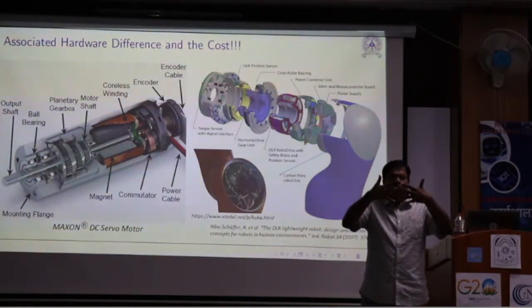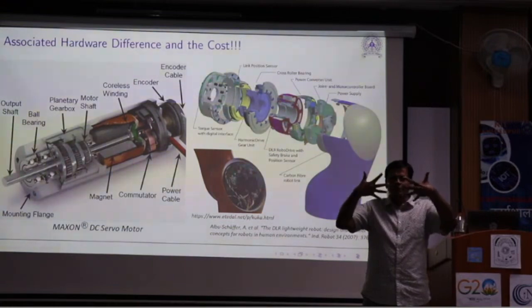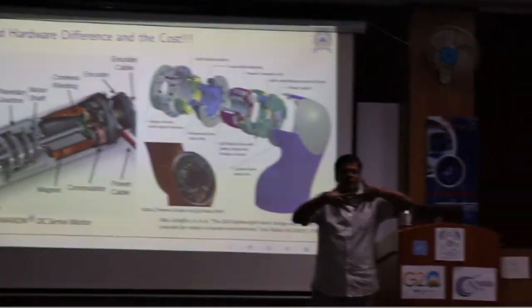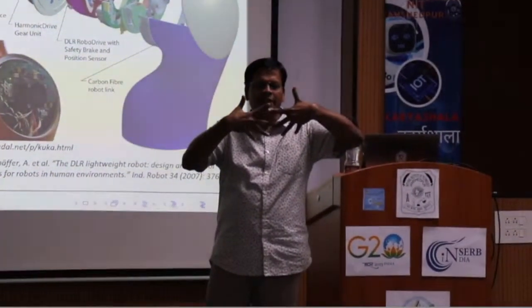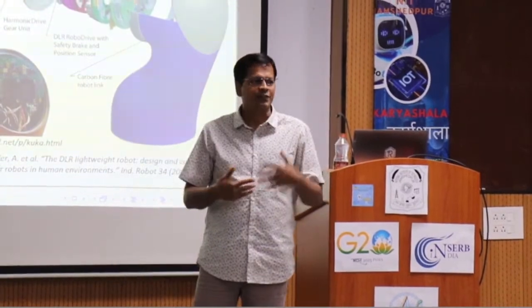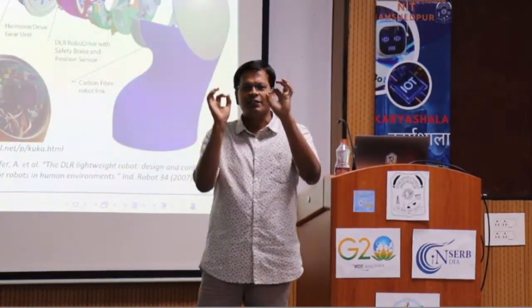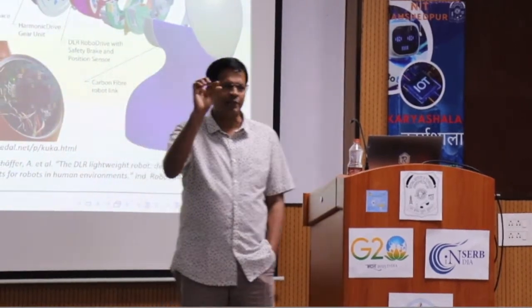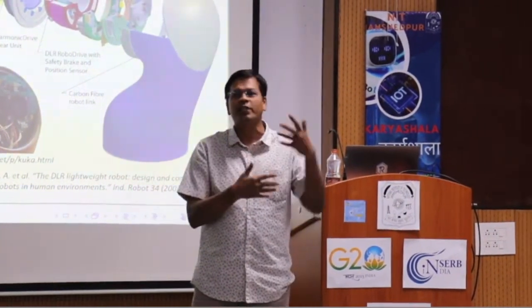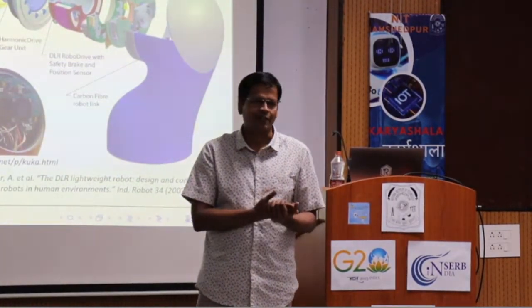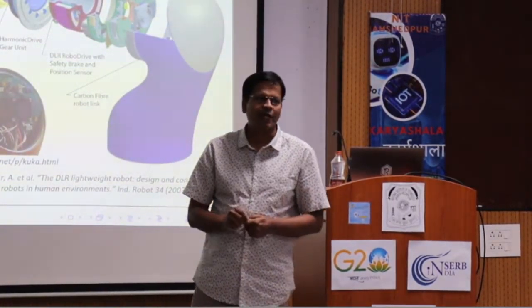There is a gap between two gear teeth. If it is meshed like this, while turning, this should be the direction. While reversing, there is a gap. It will stop in between. Now it will start moving. So between the driving and driven shaft, there is some gap. So there is a small amount of time in which there is no movement of the driven shaft, even when the input shaft is rotated. Right. So that is a small amount of backlash.